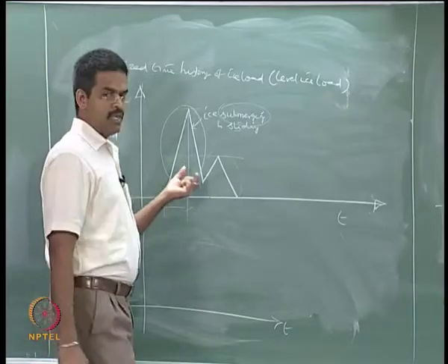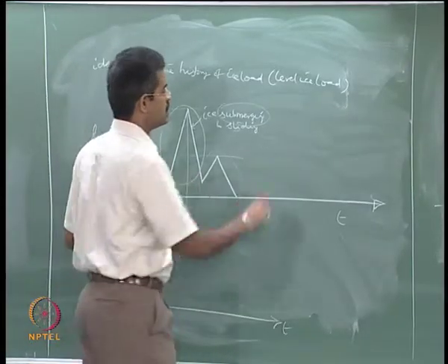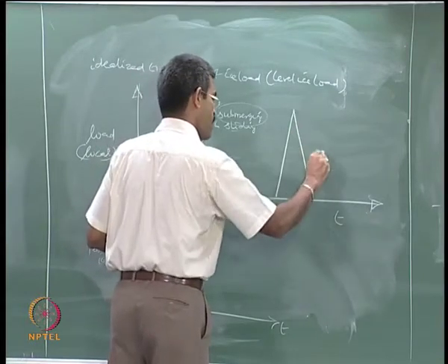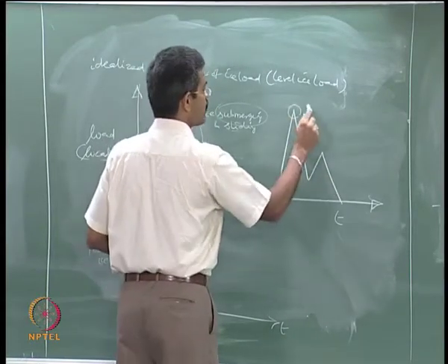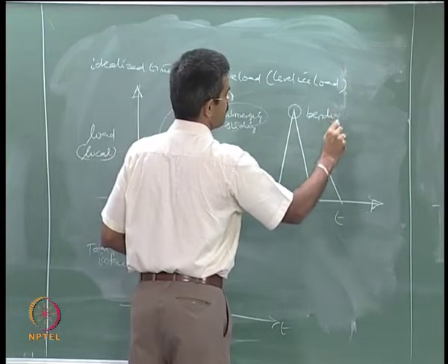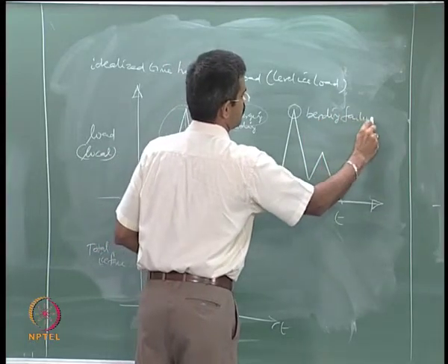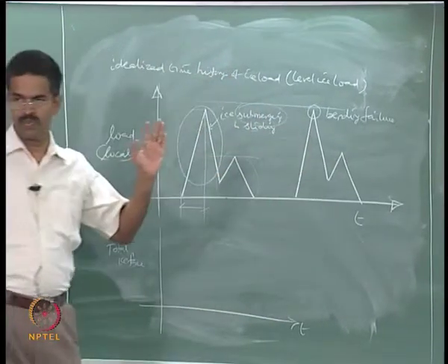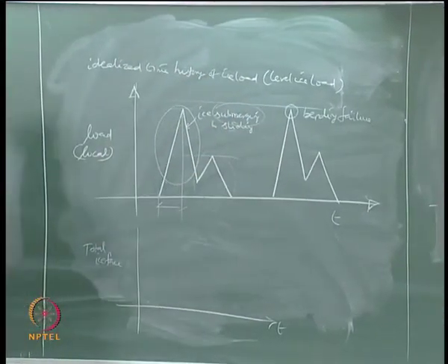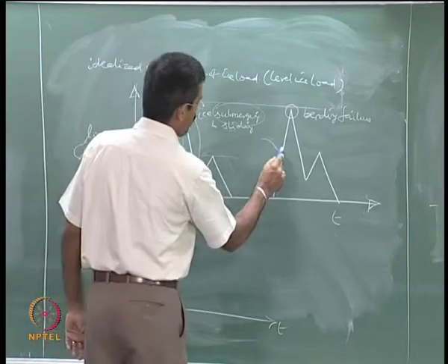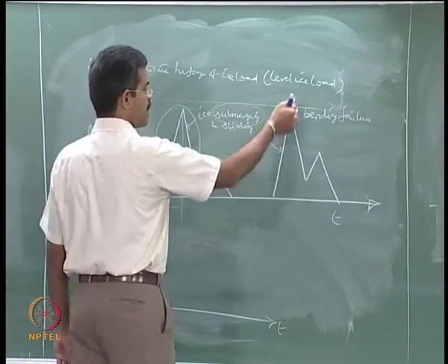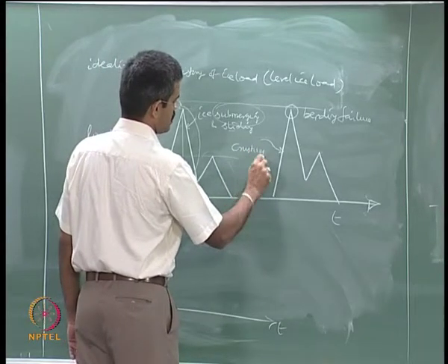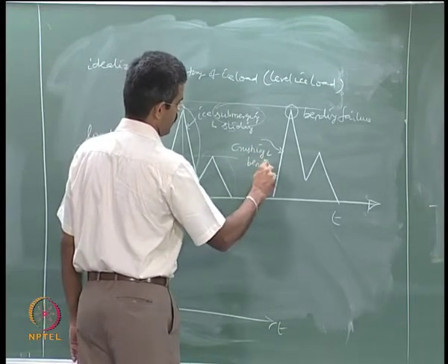If you look at the behavior in terms of its failure, then a similar curve is also existing. This is what we call as bending failure point. It is a maximum in terms of its loads, and this ascending line of the curve is related to crushing and bending together.